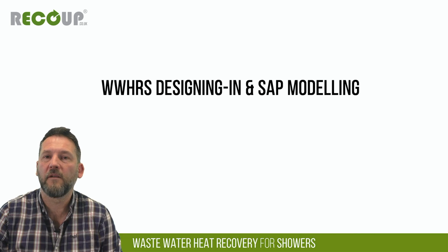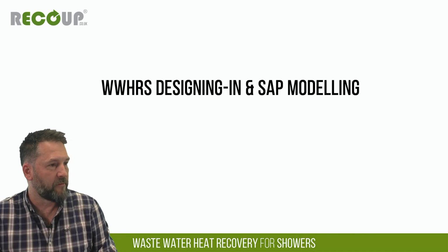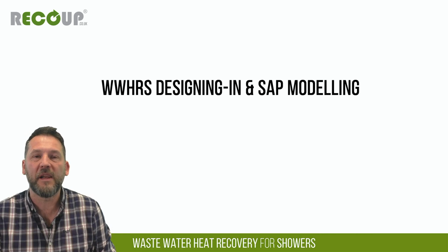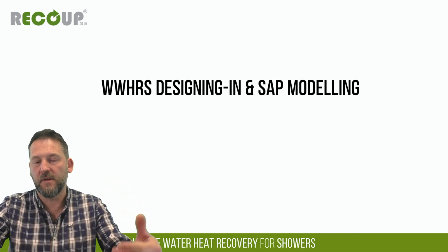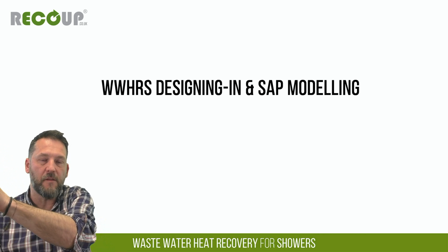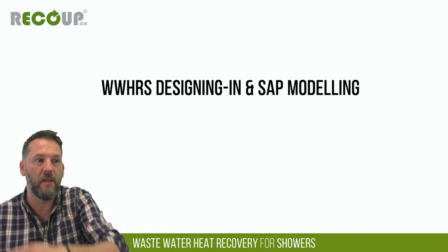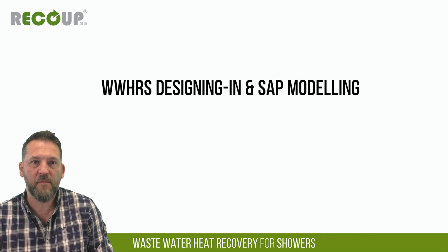One more question, Alice, was on a rough ballpark installed cost for a retrofit in terms of an Easy Fit under bath. How long's a piece of string? If it's simply a unit going under a bath where you can take the cover off the bath and install a System B, taking the cold feed that's currently feeding the thermostatic shower, relocating it through the unit and then back up again, realistically 2-3 hours of plumber's time, I would have thought.